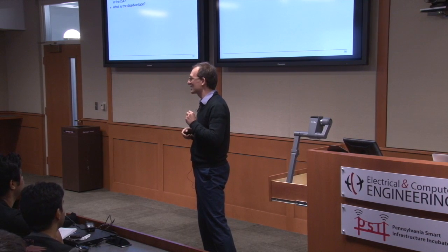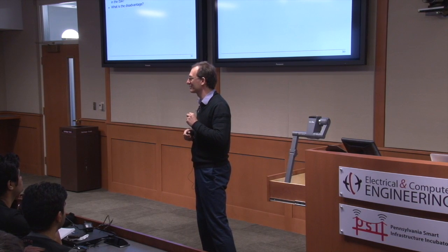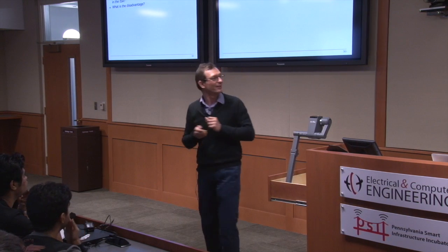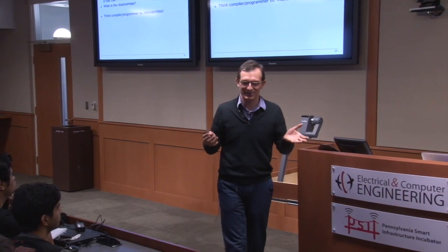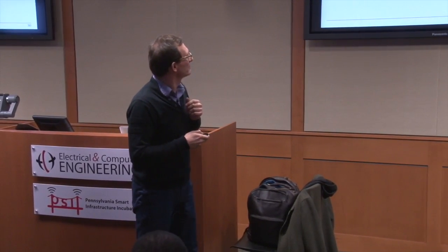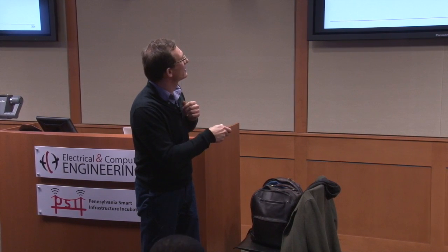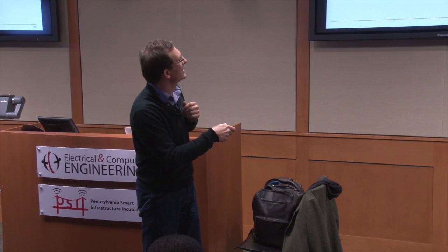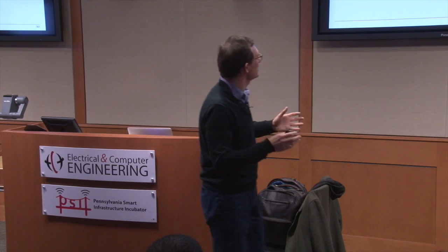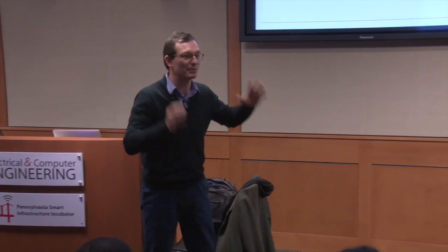Complexity, right? It could be complexity. It could be more work on the programmer, more work on the hardware designer. Again, the trade-off is between the programmer and the microarchitect, right? You're making the microarchitect's life harder by adding more and more data types, but you may be making the programmer's life easier in this case, because the programmer, or compiler, doesn't need to map a doubly linked list into small operations on integers and pointers.